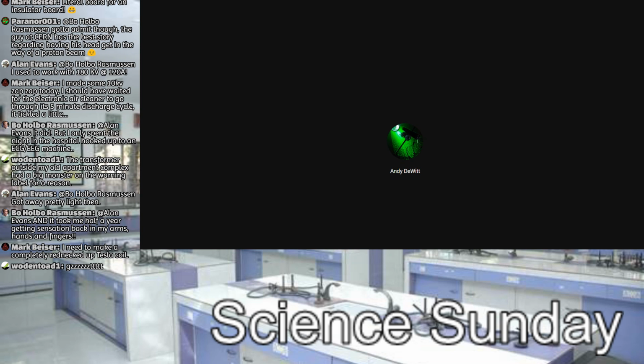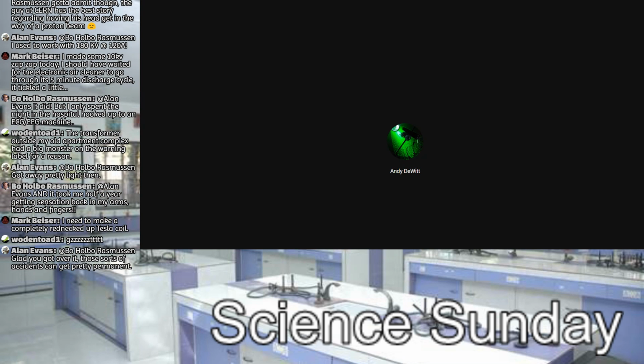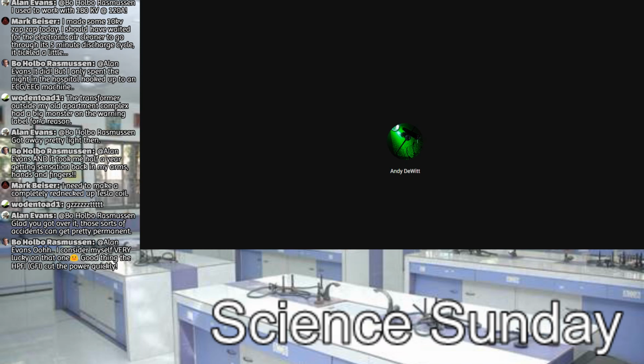I was actually tempted to haul down the old oscilloscope. I don't have a new one, it's a very old one, but this is definitely within the frequency range it's expecting. I was thinking of doing the real calibration way for these things. What we're doing is sort of what we call loose design, with the variable coil. We design it so it's close. We know it's in the range, and then we just adjust the coil to tune it to resonance. If we wanted to go all nuts, and by the way, you end up with the same results if you do it the alleged right way.